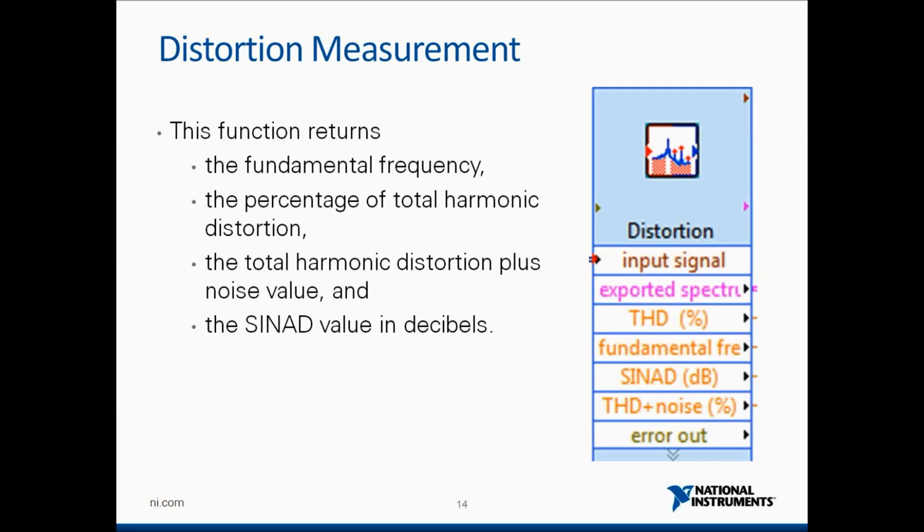Fine, let's move forward. The third one is power spectrum. As the name suggests, it calculates the power spectrum and the power spectral density of the input signal. What this basically means is, at each particular frequency, how much power is contained, which is proportional to amplitude square. The output of this is a graph which shows you how much power is present at a particular frequency.